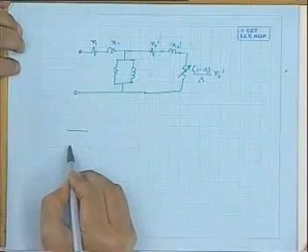So from that input power, you subtract the stator copper loss, then you subtract the core loss power. These two losses you subtract. That remaining power, as if it crosses the air gap, now enters the rotor. Like that you just conceptualize.